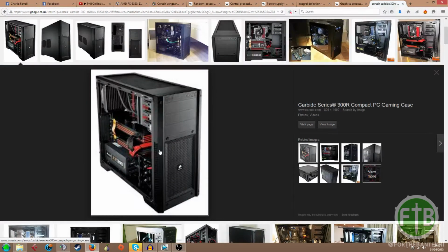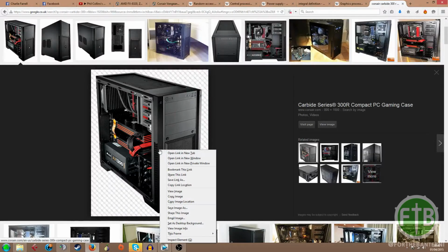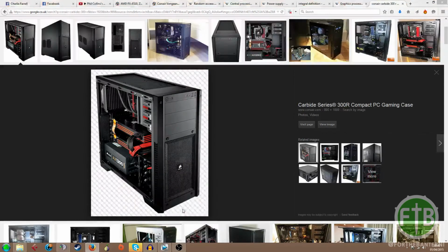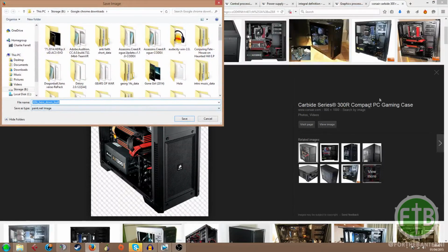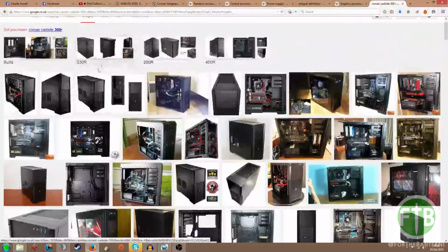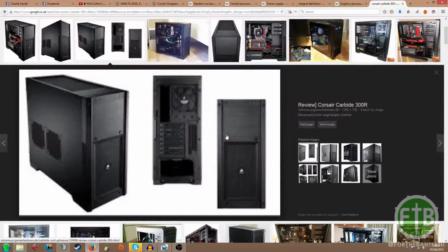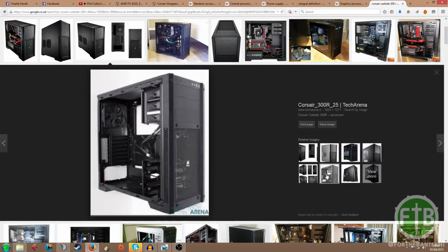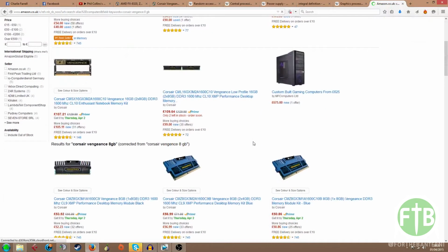Okay, so although I've picked out these parts, some people that haven't a clue about computer parts will go, well, how did you know how to pick these parts? Well, the only main thing you need to worry about when building a computer is the processor socket and the motherboard. Motherboards are built specifically with one given processor slot, and they are also built for a particular company's needs. For example, I use an AMD CPU, so I need an AMD based motherboard made by an aftermarket company.